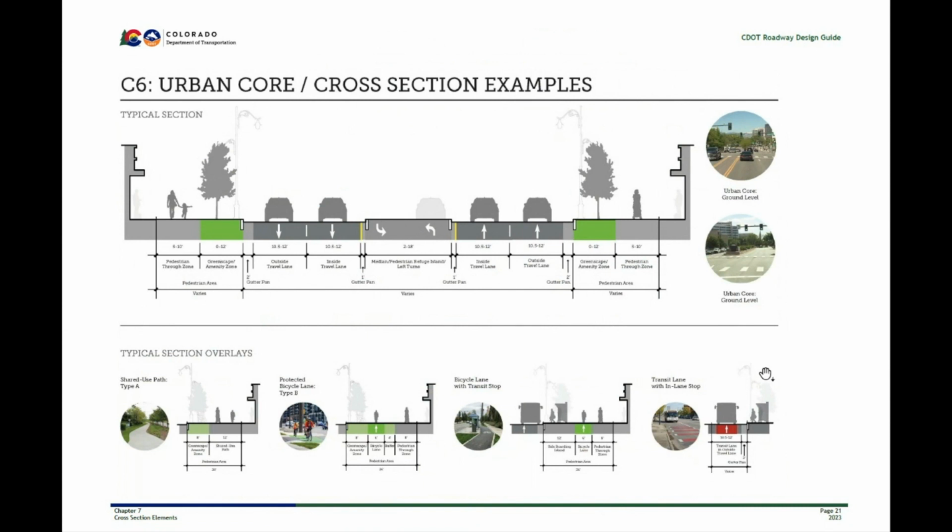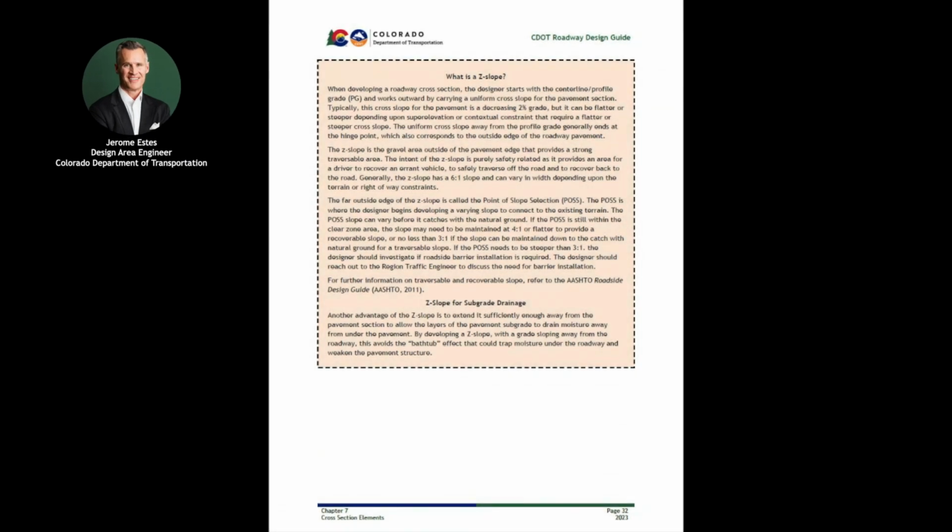Just a few items to keep in mind when completing this step in the project process include the optimal lane and shoulder widths and surface types, clear zone, drainage aspects, multimodal accommodations, barriers, and transit operations. The consideration of the clear zone with the roadway design and implementation of curbs is another element to examine when developing sections adjacent to safe drainage channels and side slopes.